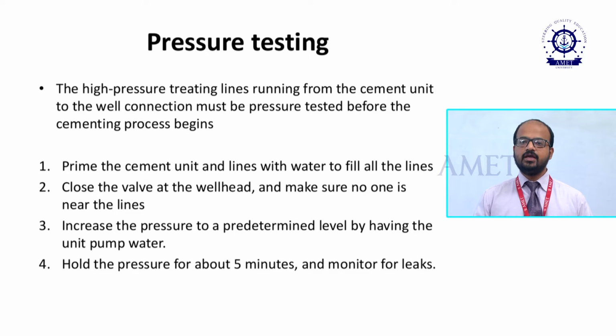So if it stays 5 minutes without the pressure decreasing, you can understand that there is no leakage. But if the pressure is dropping, which we can see through the monitor, then you can understand there is some leakage. Through the leakage, your water starts to go out. So now you have to go and check where it is leaking, and you have to fix it, because this is needed when we are going to do the cementing job. We have to ensure that the cement does not go away, it should only go to that particular well.